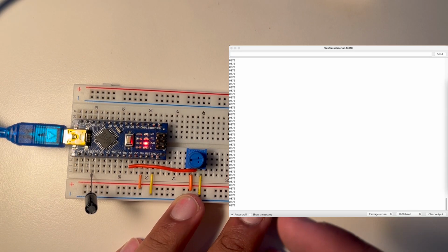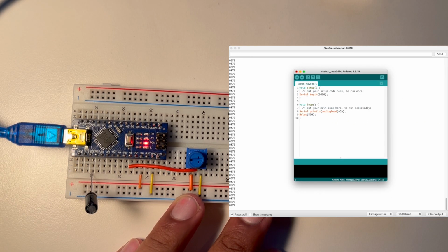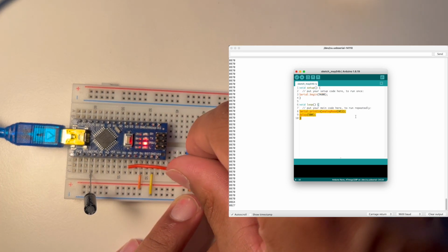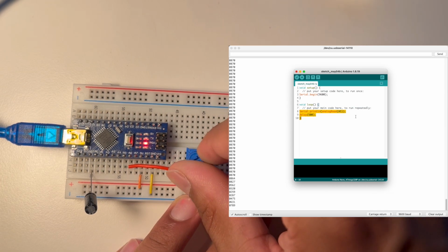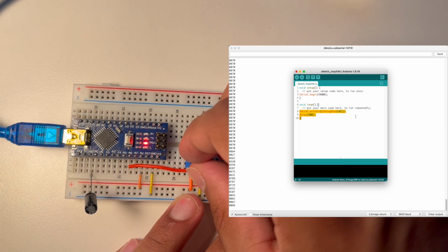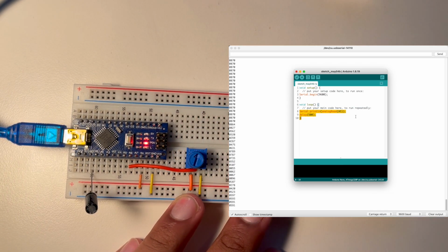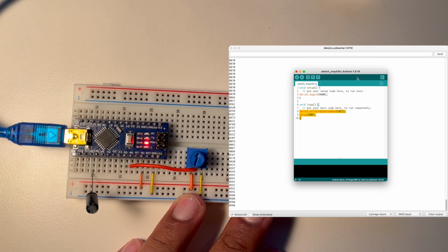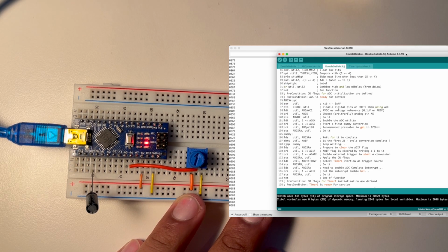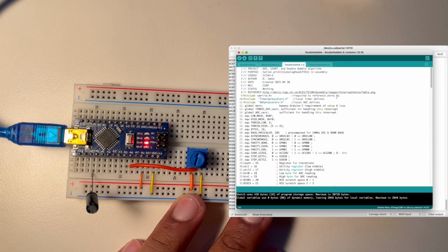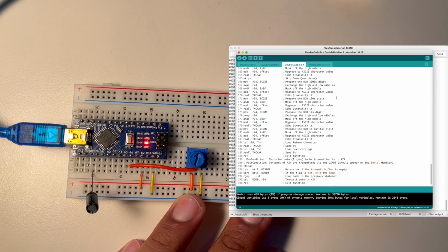And at first glance, you might think that the program being run on this microcontroller is this program right here. We're just doing serial.begin, then constantly printing the value of analog read and waiting 500 milliseconds, hence the updates as I spin the potentiometer every 500 milliseconds or so. But in fact, this is not the program being run. This is the program being run, which is quite a bit more complicated and around 200 lines long.